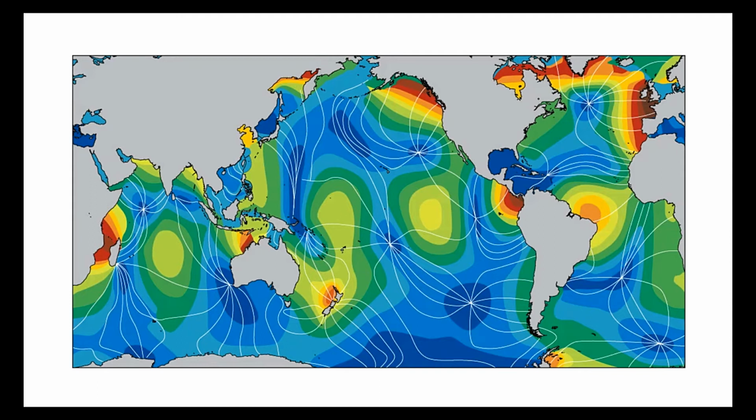You've got to make sure that you can still navigate the channel in most of these places as well, which causes trouble. And then there's the debate whether you have the turbines floating from the surface or mounted on the ground. If they're mounted on the ground they're out of the way, but they're closer to the sea floor, so they're harder to maintain, and the flow is actually lower on the sea floor because of the boundary layer from the friction from the ground. Then at the surface, you've also got waves, so you've got to weigh these things up. I think that's part of the reason why no one's really decided on it.